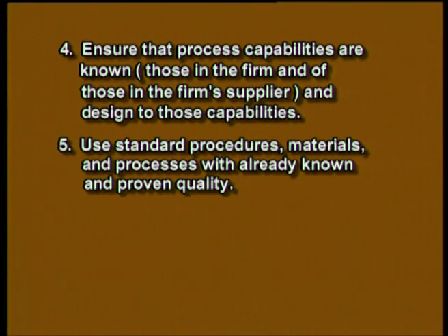And then use standard parts, standard procedures, a lot of advantages. If in designing a new product you use existing components, you do not have to make new tools, do not have to come up with a new material. So, you can use them and achieve savings in both design cost and manufacturing. You could be creative while using standard parts. Some people think standard parts means inflexible, same old, old wine in a new bottle.